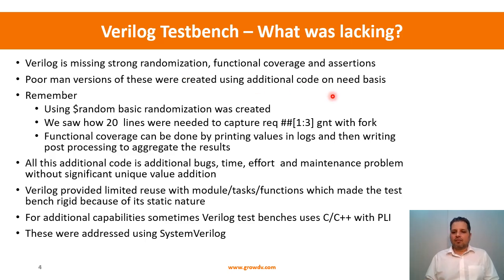They wrote additional Verilog code, and they utilized capabilities like interfacing with C++ using PLI, so that they could exploit features present in other languages. C++, for example, is object oriented, so you can build part of an object oriented testbench using C++ and interface it using PLI. People did such things, and that's what led to evolution.